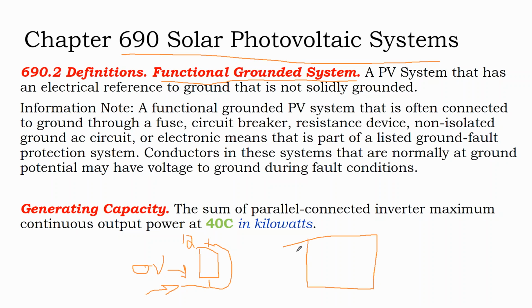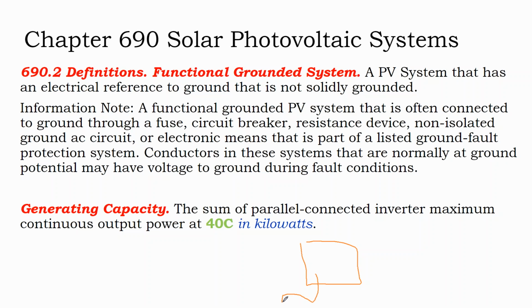Well, with solar inverters, they were taking that negative side and connecting it to ground, and that was resulting in a blind spot failure case for the inverter ground fault detection, where you had small ground faults going into ground, raising the voltage potential of that ground, and the inverter wasn't able to see it clearly. They've since fixed this inverter blind spot issue by not connecting the inverter DC negative side to ground, but having it be isolated.